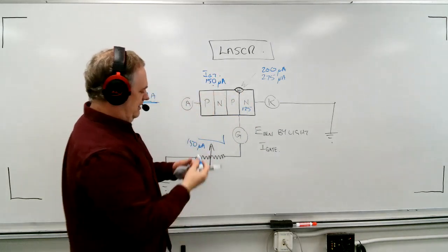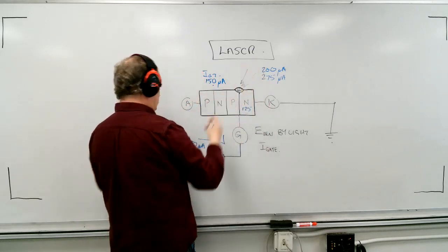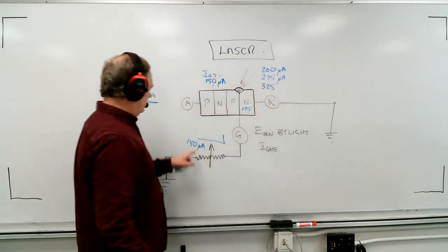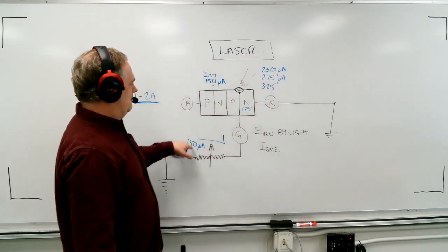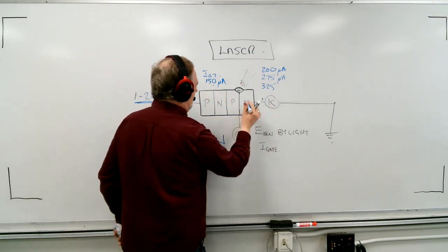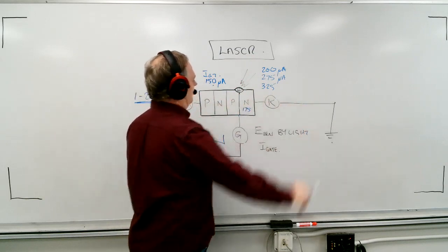So you go, oh, okay. So we need a little more light. And sure enough, that takes us over. Let's say this goes up to 325. We're still draining off 150, but it means we have now 175. So we have now enough, and this fires and the SCR starts to conduct.